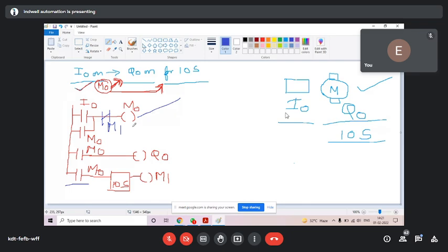That's why I told you, when you get the last signal, break latch. If latch is broken, everything below latch will get off. And here we have one latch. In a big program, you might have many latches. So when you get the last signal, you should break all latches, not only one. If all latches are broken, everything will get off lastly.